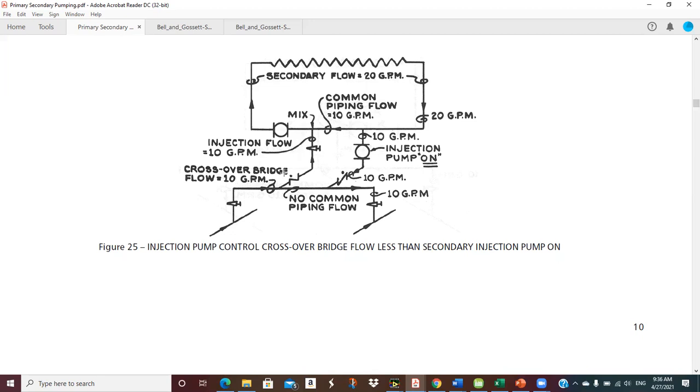So let's say this was 200 in the primary, and let's say this is sized for 140 leaving coil temperature. That's a 60-degree delta T, so half of that is 30. So I'd have about 170 here that's being pumped into the coil. Then the coil would see 170 minus 140, or a 30-degree delta T. That's the way that works.